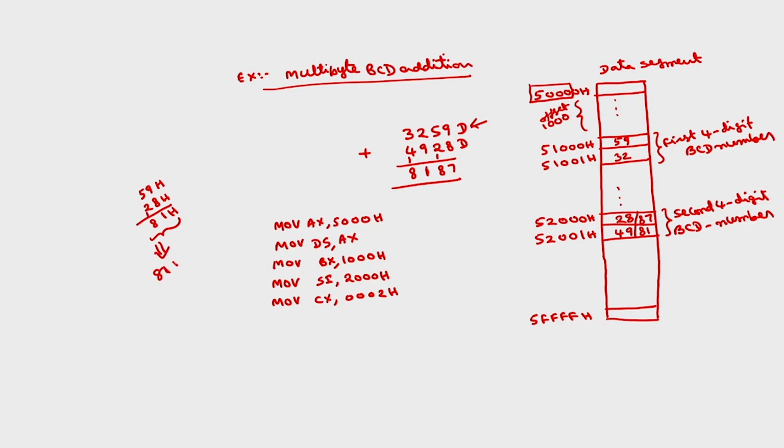we have discussed the instruction. So, which instruction will be used? There is an instruction called DAA. This DAA instruction operates only on AL, which is only 8-bit data. That is the reason why I am performing this 2-byte addition.